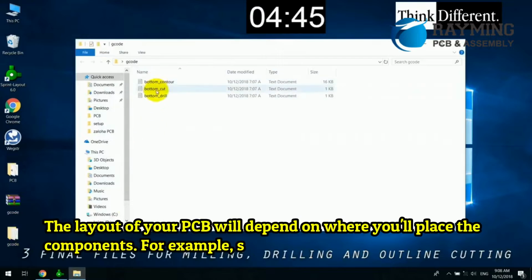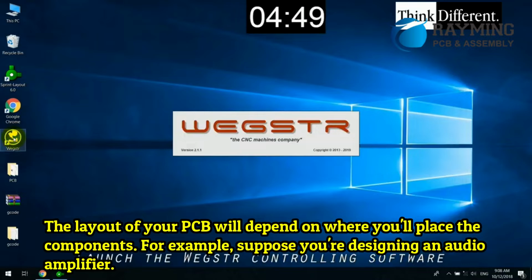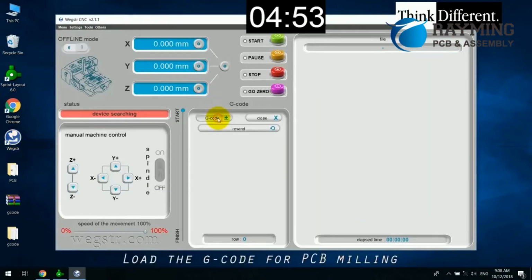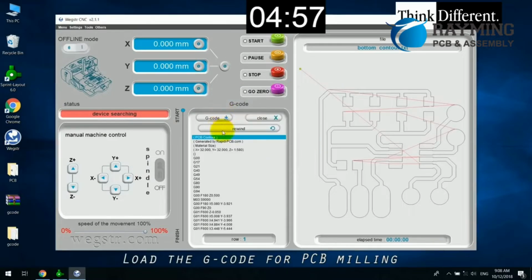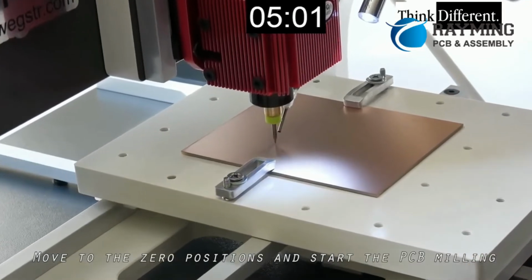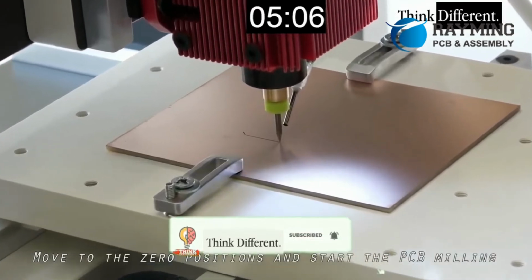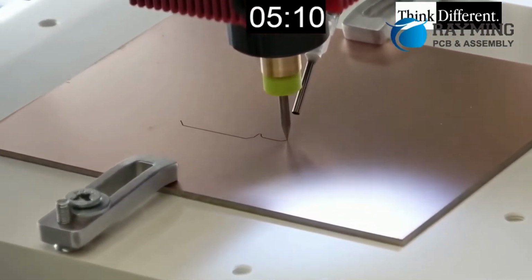The layout of your PCB will depend on where you'll place the components. For example, suppose you're designing an audio amplifier. In that case, you may want to place the power switch near the volume potentiometer so that the LED will indicate whether the power switch is on. However, larger circuits are more complex, and a single copper layer may be insufficient. Often, 2 copper layers will be necessary, and traces will need to be routed on both sides of the board.